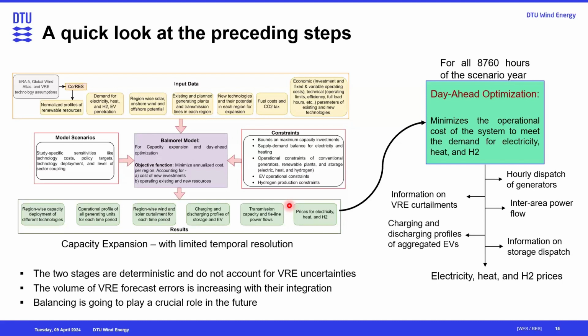What does that mean? That you also have room for reserve coming from wind and solar. And then there is also inter-area power flow between the countries. Why is that important? If there's an imbalance, I look at my interconnections between Sweden, Norway, and Germany, and I know how much support I can get from my neighboring region.